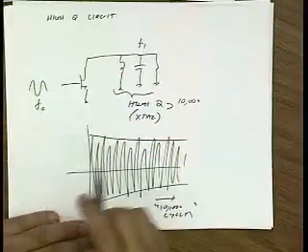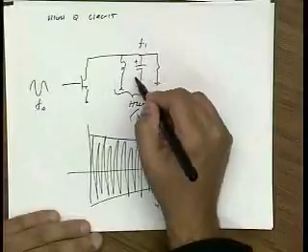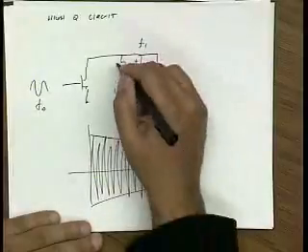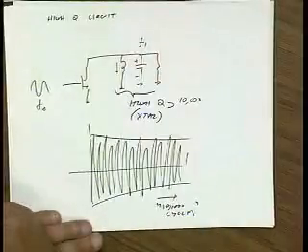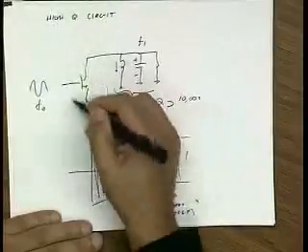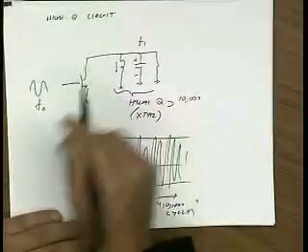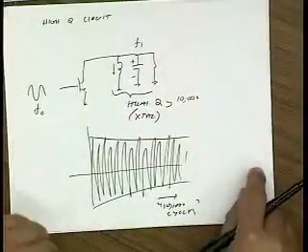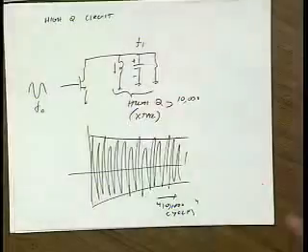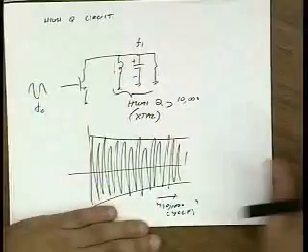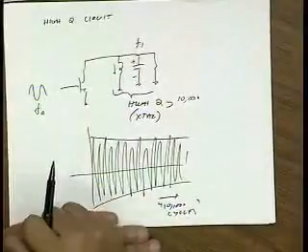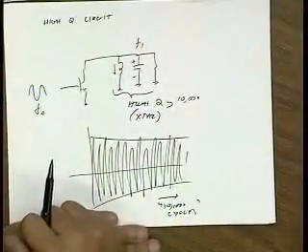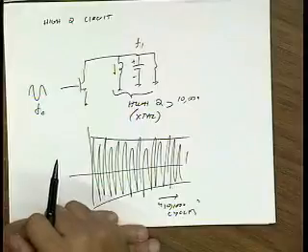On the other hand, if I could find the final charge on this capacitor and current in this inductor, and also the same inside here, all the voltages across the capacitors in here, that result in periodic steady state, I could just apply those voltages and boom, the circuit would be in periodic steady state. It wouldn't ring at all. So that's the idea behind PSS. Okay, any questions? That makes sense?